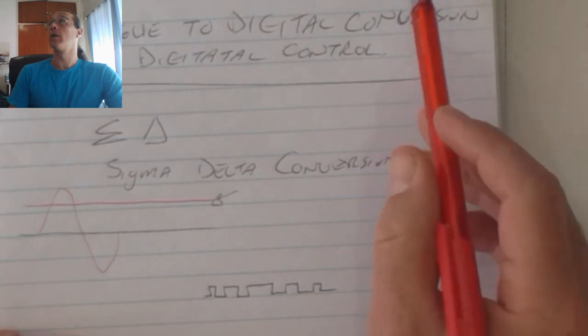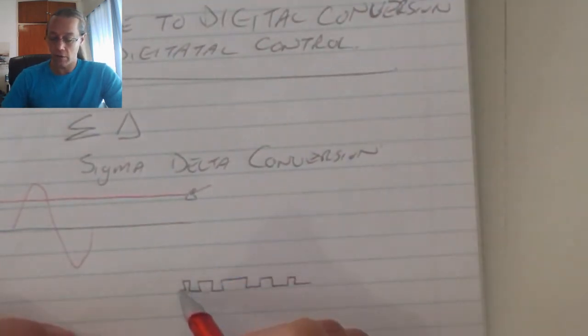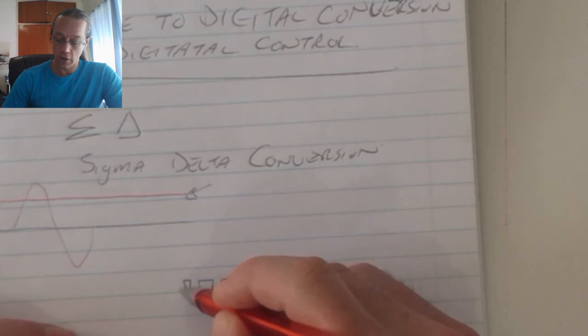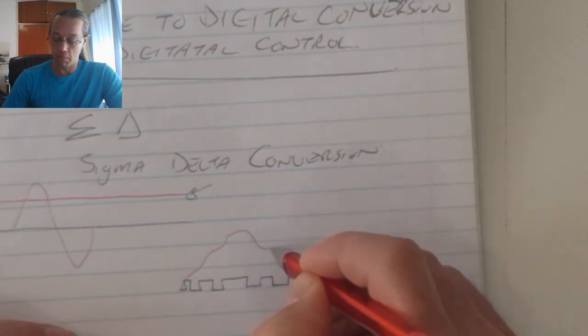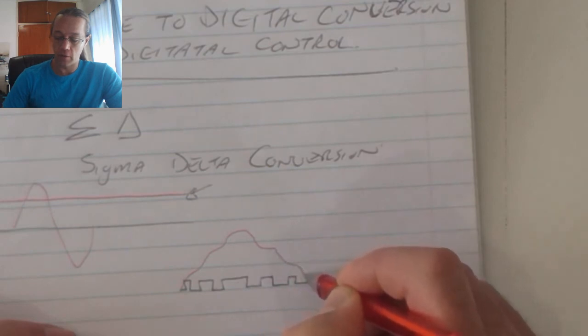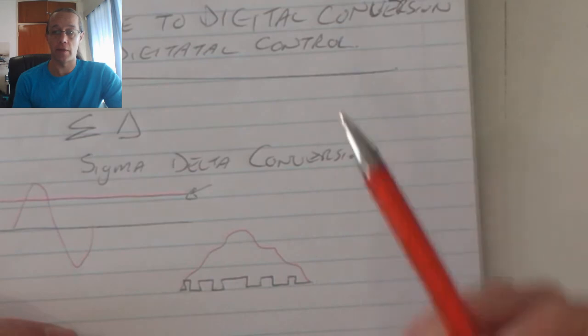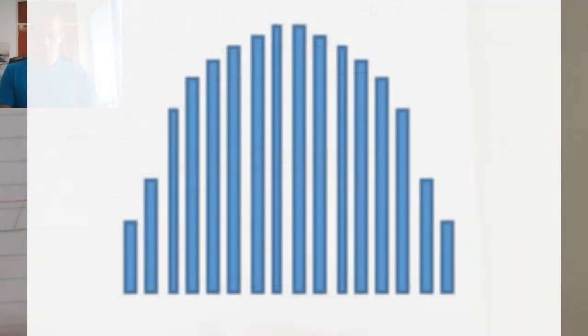In the inverter, we will have a capacitor that has the ability to charge. So the longer the pulse is introduced onto that capacitor, the more that capacitor will charge. So we will get a modified sine wave generated instead of a pure sine wave. So the string of pulses will then generate the sine wave.